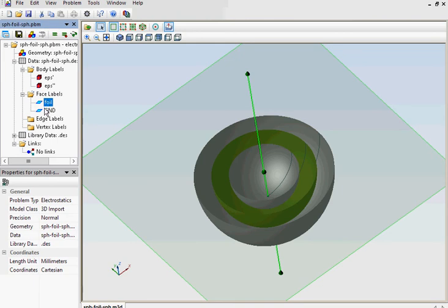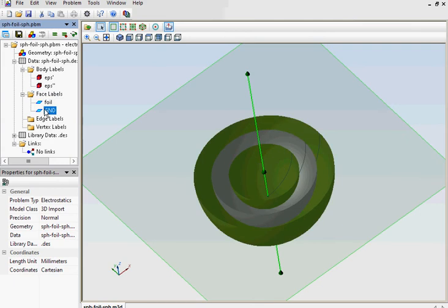Now I will click the label grounded. The internal and external sphere surfaces are grounded. Epsilon 1 is the internal layer of the dielectric. Epsilon 2 is the external layer of the dielectric medium. The model looks alright. Next we should build the finite element mesh.